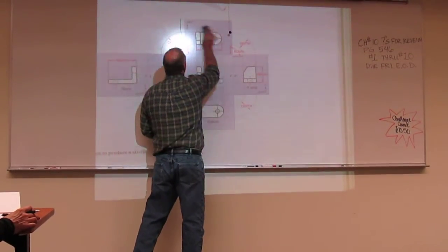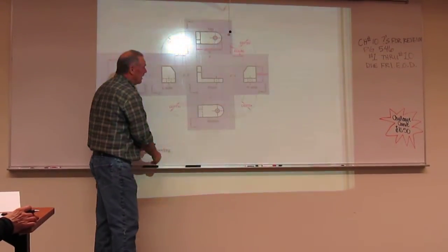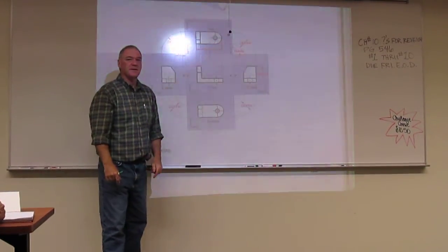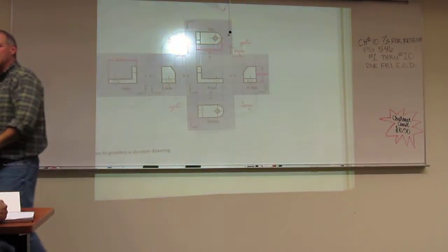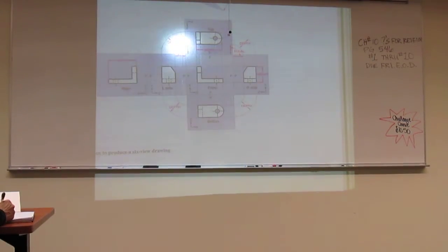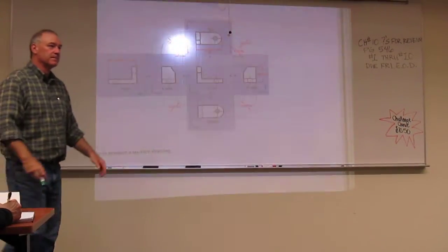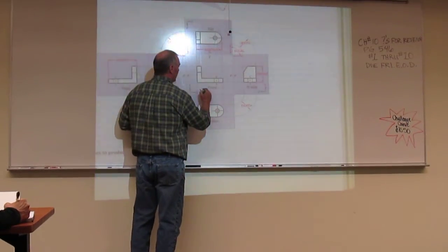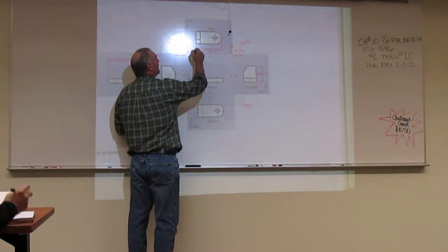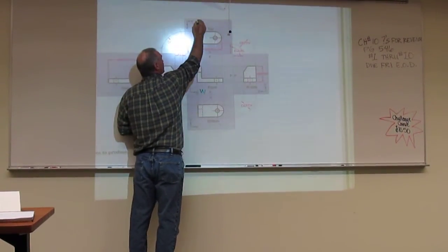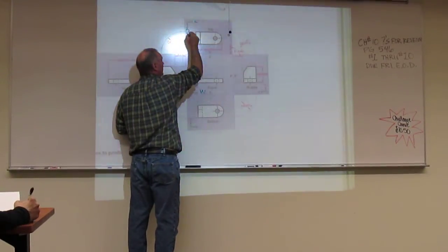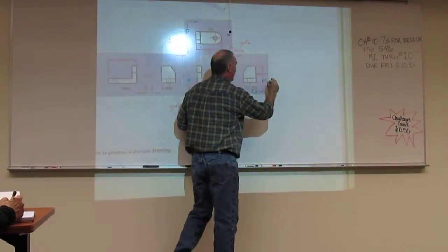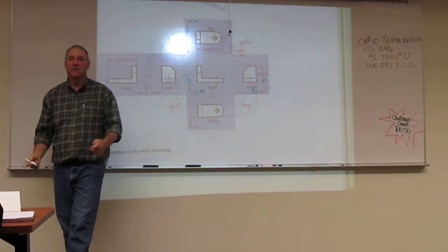Now with these same three views, these we call our primary views: front, top, right. Why do we call these our primary views? Because those three give us all possible combinations of the dimensions together. So remember, this one right here has x, y, or width, height. This one has z, x, or width and depth. And then this one over here, depth and height. Those are all your possible combinations.